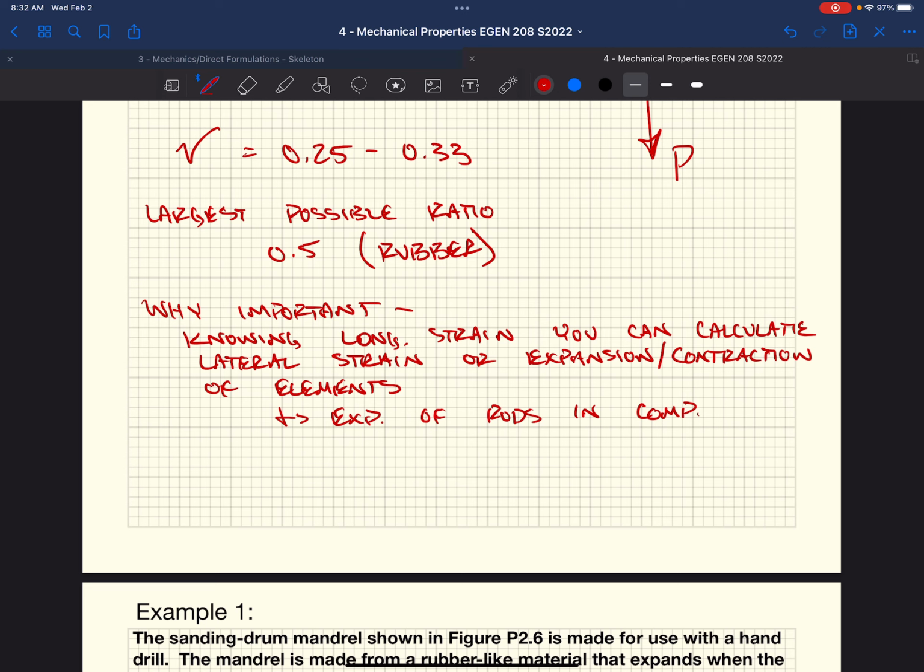So we have this idea of the modulus of elasticity, right? Have you guys talked in your materials classes about the shear modulus? Okay. Very similar, right? The elastic modulus, Young's modulus, is our normal stress over our normal strain. Well, our shear modulus is our shear stress over our shear strain, right?